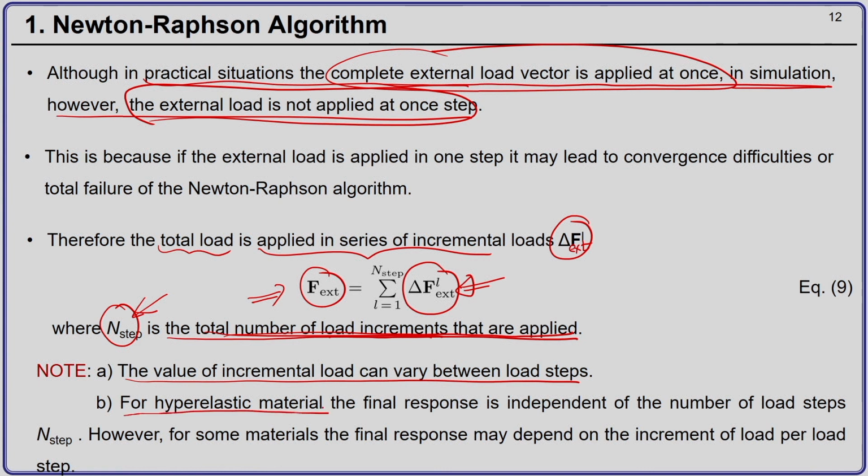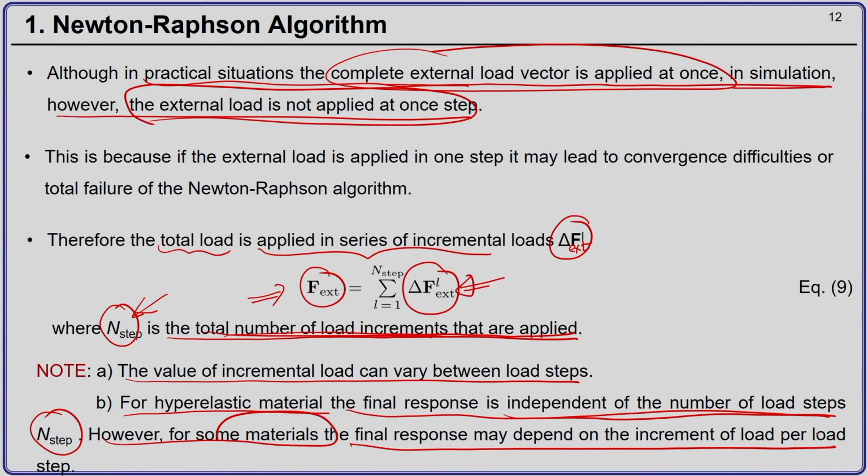For hyperelastic materials that we have in this course, the final response is independent of the number of load steps that you take. Okay. Because the response for hyperelastic material only depends on the initial and the final point, and it does not depend on the path you take. So, your final response will be independent of the number of load steps that you take. However, for some materials, the final response may depend on the increment of load per load step. Okay. So, there are certain materials for which your response will be different if you take different load steps. Okay. That you need to remember.